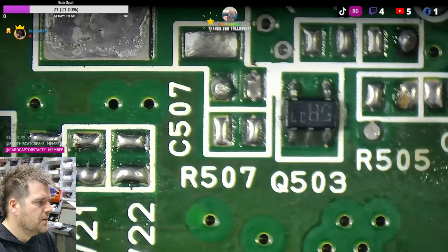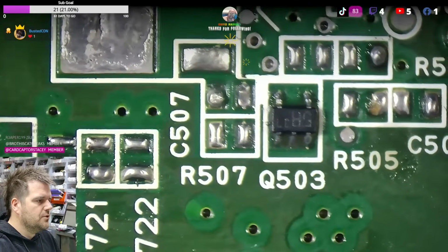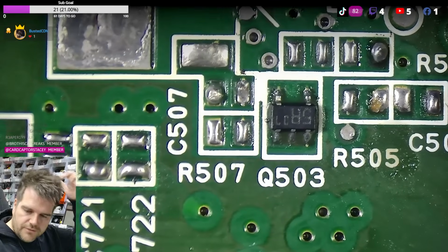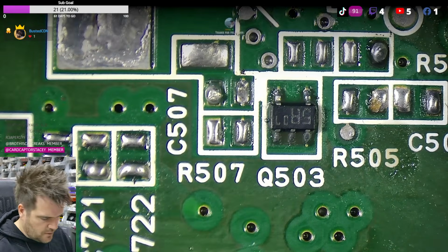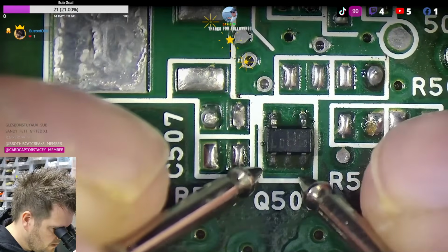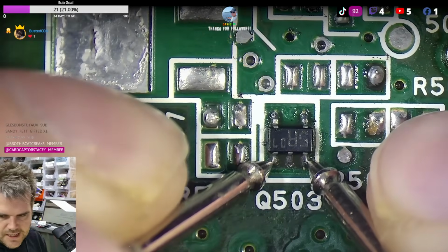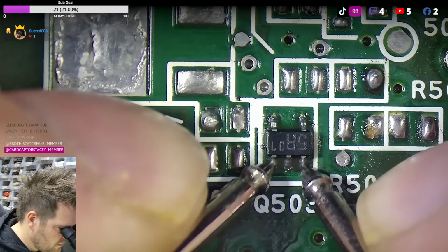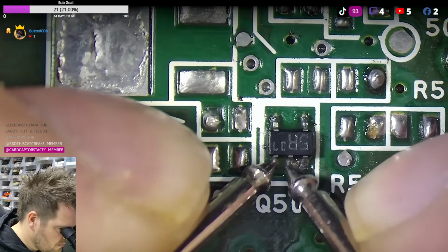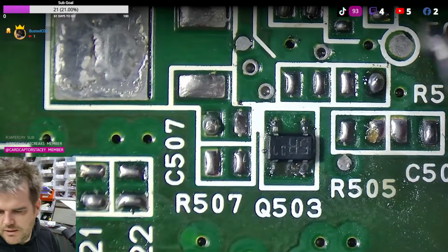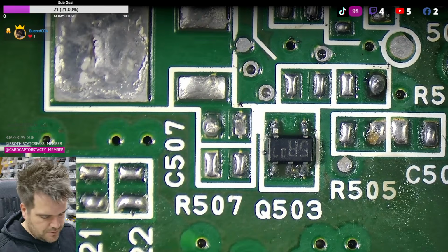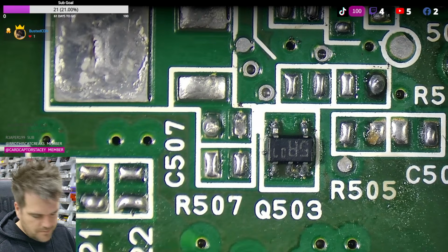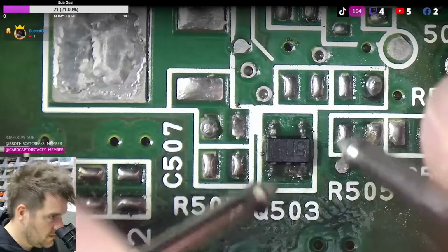I wonder if that's similar. I wonder if all these are epitaxial transistors. If they are, then a typical sign for quick reading is if we go over the outer 2 pins, we get a high resistance. Now we're getting nothing, so it's not that. Let's put it in diode mode and see if we can spot any diodes on any kind of layout.